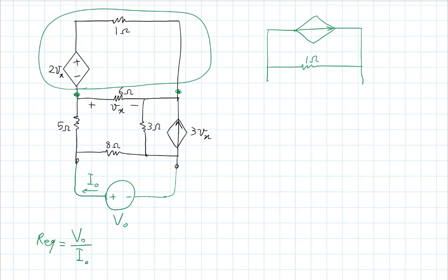The value of the current source is what? In the Norton representation, recall that the open circuit voltage was just Rn times In, like the example we saw earlier, right? The open circuit voltage in the Thevenin representation was what?